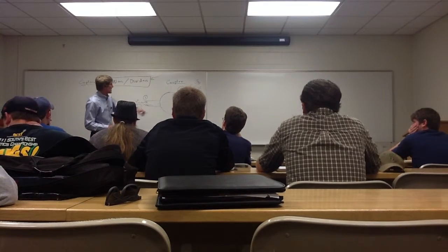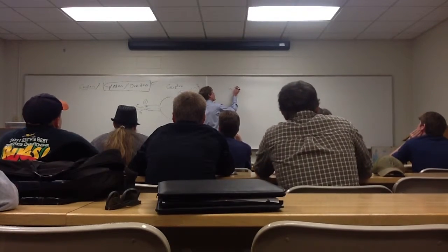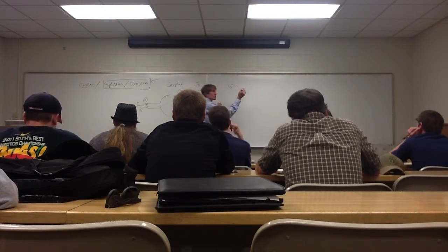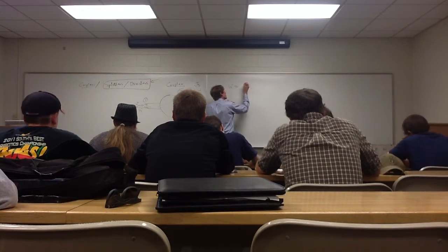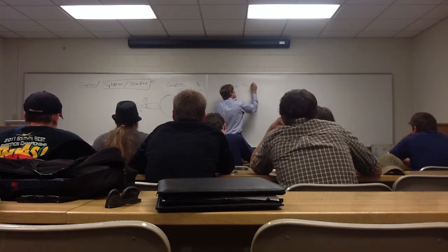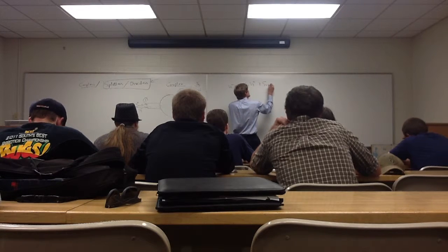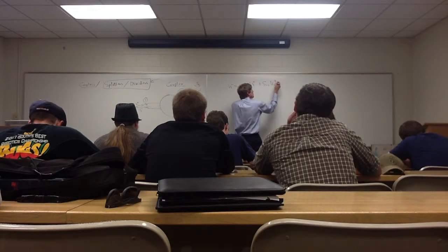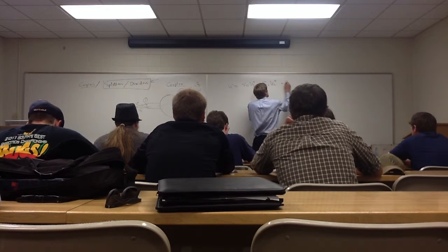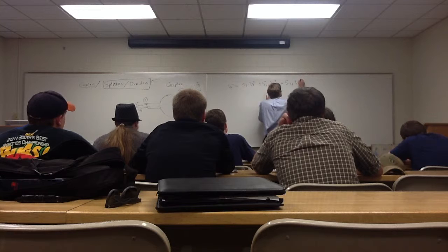So if you have this, I'm going to start by setting up the equation. V1 minus would be equal to, and the general way we did it was 2 by 2, you always start with S11, that's the reflection coefficient, times V1 plus, then plus S12 times V2 plus, plus S13 times V3 plus.